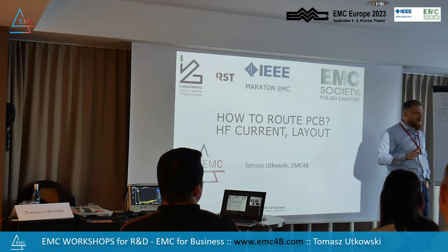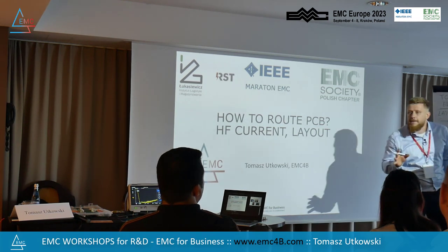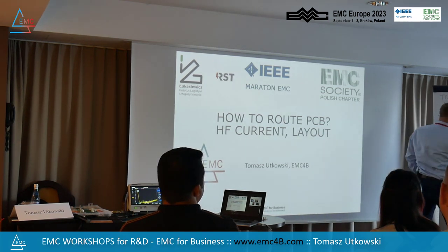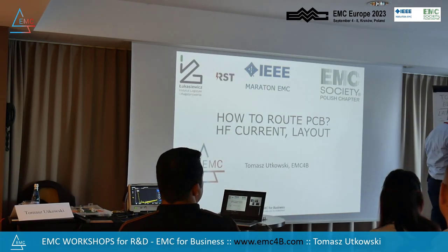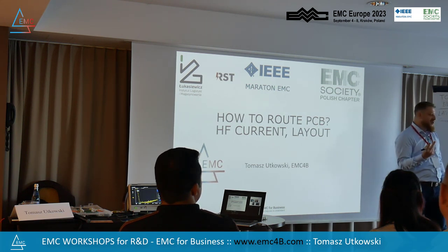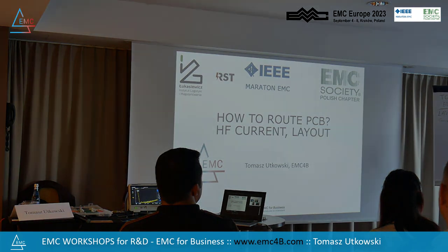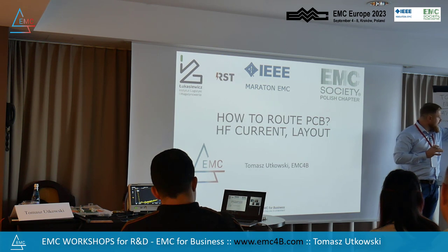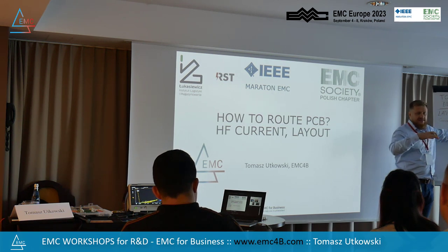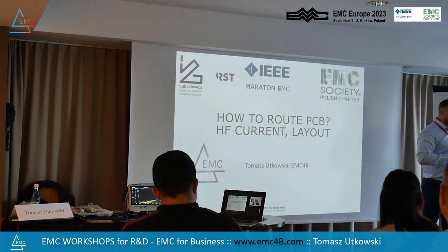What kind of components are in the filters? Chokes. Chokes mean inductors. And second, we've got only two components in EMC, mostly: chokes, like inductors, and capacitors. Ferrites I think of like chokes, inductors. And also for ESD, TVS, varistors, and so on. But okay, so we've got two kinds of components we place on the schematic.